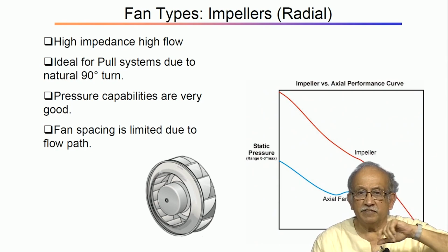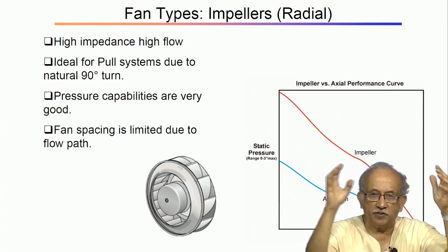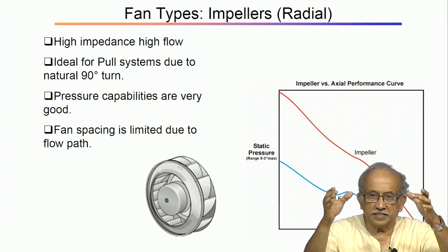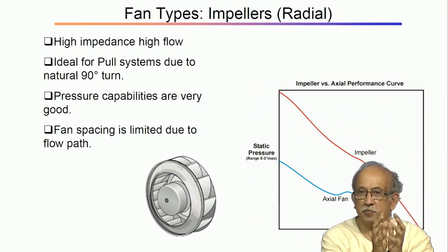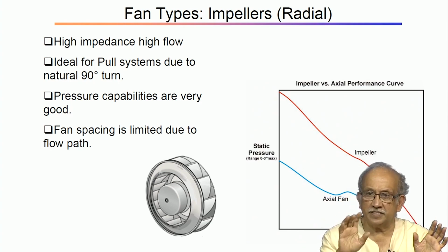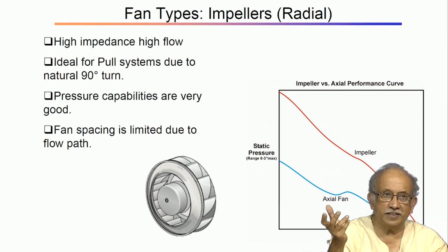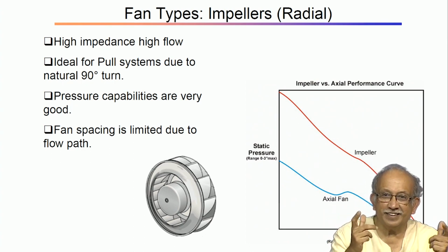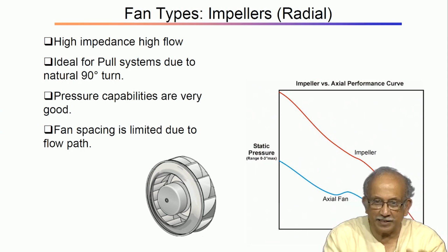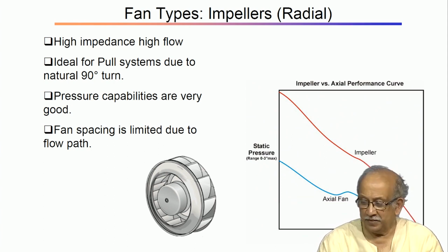You must have seen all those whirly bird ventilators on several roofs. The advantage of the whirly bird is that naturally there is something rotating, and air starts exhausting. Both versions are there. There is one which is helped by a small built-in motor, and there are some which are motorless. As the air from outside comes, it acts like a natural windmill. Yes, I too had the doubt. A windmill impedes the airflow, but at the bottom you already have warm air rising. So, that is how a whirly bird works.